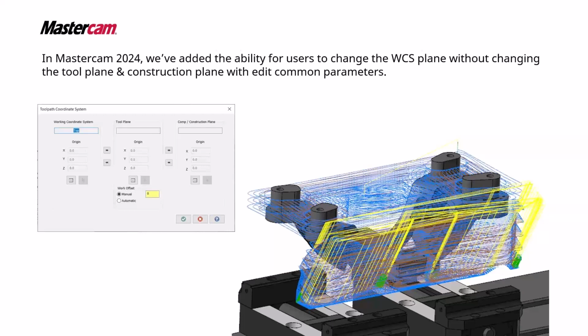So it meant that we had to change the WCS plane. And this was a 5-axis part, so I was using tool planes and construction planes. I wanted to be able to change just the work coordinate system without affecting any of the tool planes or construction planes. So let's take a look at that.